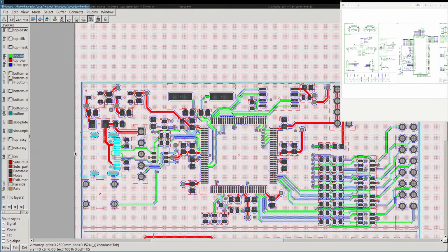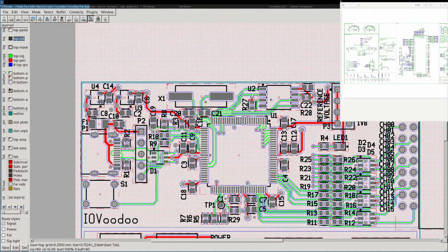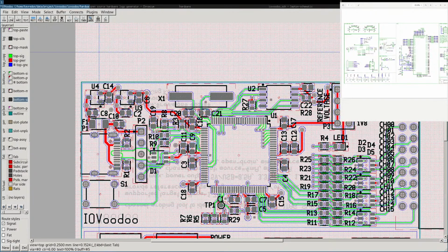And these are things you have to check afterwards, and if you just do the layout, these are things you don't see immediately. If you just look at the tracks, there's nothing there. So don't forget, look at the solder mask, look at the silkscreen, solder paste.